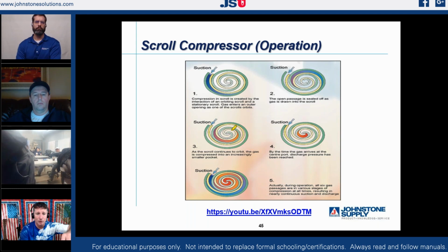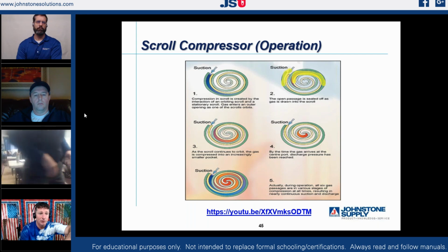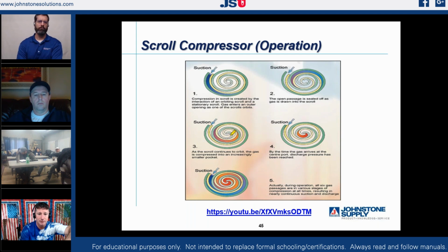As we move along, see now, as this vapor is passing through this portion of our compression, we're now reintroducing pressure over on this side. And as we move along, we just keep doing that. We move it along so that we not only have one compression in a revolution, we have one here, we have one here, and we have another one out here. So we have multiple compression cycles going on inside of this pump.